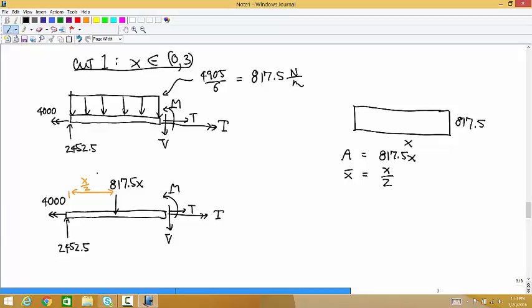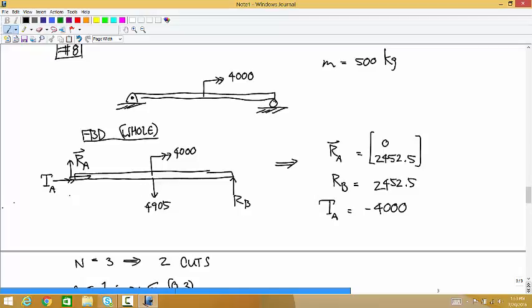Any other questions? Anytime you have a mass represented, it's automatically one more cut, and you can do that on the midpoint. No, actually, that's an easy mistake to make, so be careful about that. When you have a mass, that's a uniform distributed load, so that distributed load doesn't change over the whole length of the beam. And so the weight never adds another cut. It's easy to think that it will, because when you treat that weight as a point force, it acts at the middle.